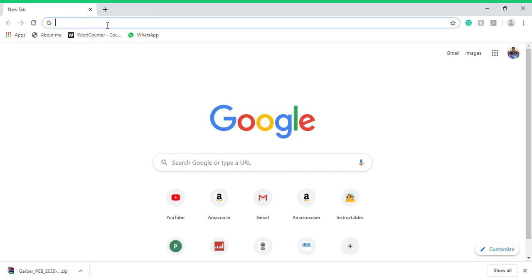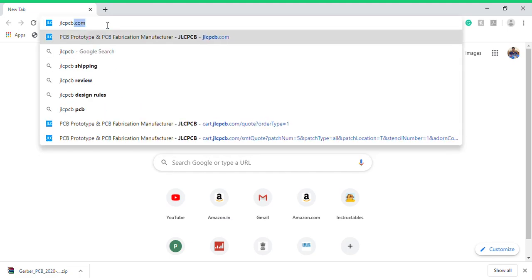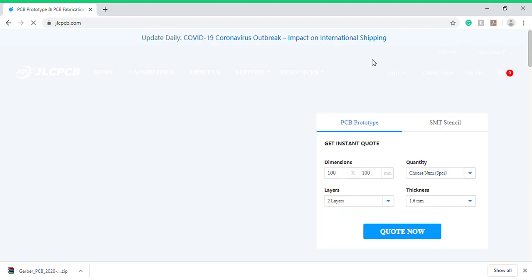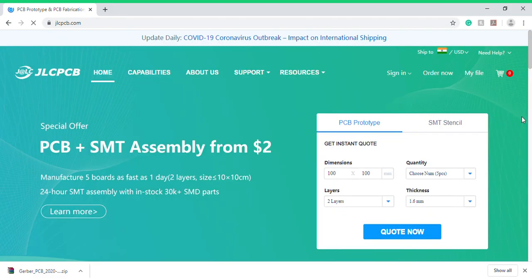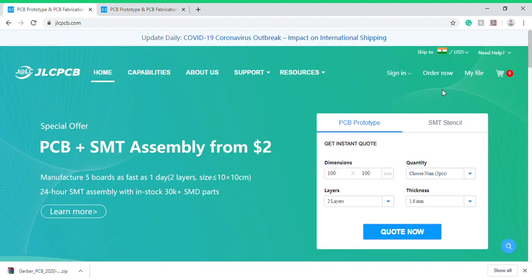I'm going to go to jlcpcb.com. You need to click. You need to again create an account. So there's a problem right now due to the COVID-19 outbreak. But I'll show you how to do an order in the normal case of ordering a PCB. So you need to click on quote now. First, you need to create the account and then click on quote now here.